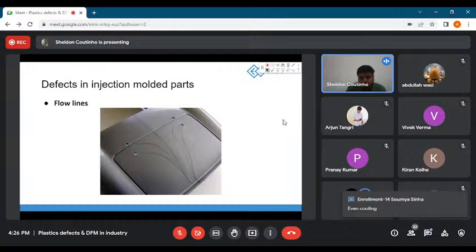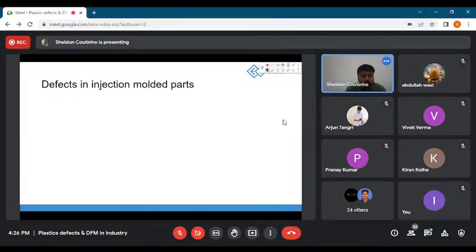Yes, even cooling. Yes, Soumya, you do want even cooling, and these are the ways that you can attain even cooling. So I'll just run through it again. You can have heated molds, I mean, molds kept at a warmer temperature. Second is to increase the injection speed. So these will be the two best options to avoid flow lines.